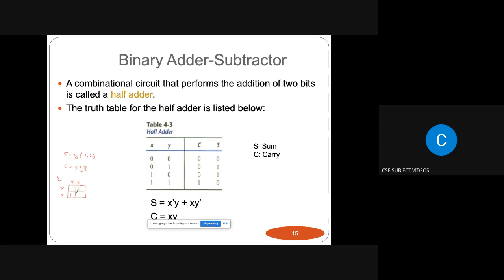In this 2 variable K map, we have to check for the quad possibility. We don't have any quad here. Next we have to check for the pair possibility. We don't have any pair possibility here. So the last is the single one possibility. We don't have quad possibility and we don't have pair possibility here, so we are going with the single ones. Here is a single one and here is another single one.